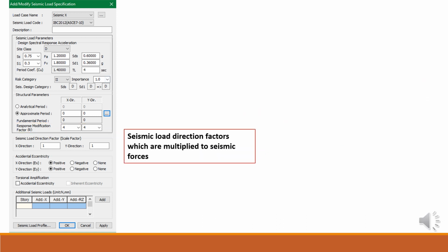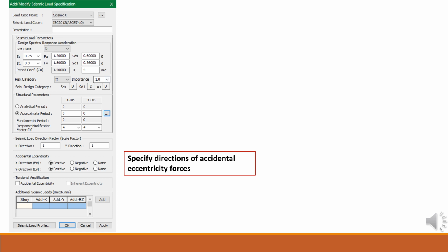This section allows users to input seismic load direction factors which are multiplied to seismic forces. Specify directions of accidental eccentricity forces.